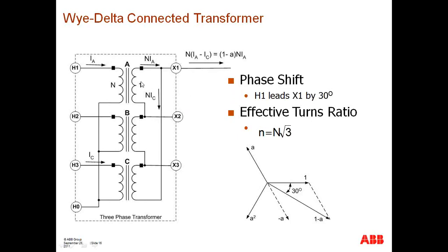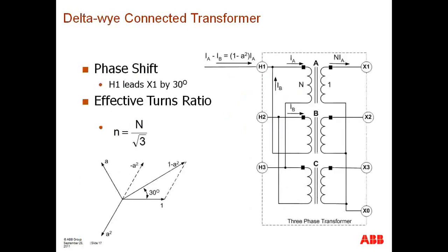And the reason for that is because the zero sequence current will be trapped inside the delta and will circulate for the duration of the fault. So again, it's a means to segregate, to separate the zero sequence network between two systems.